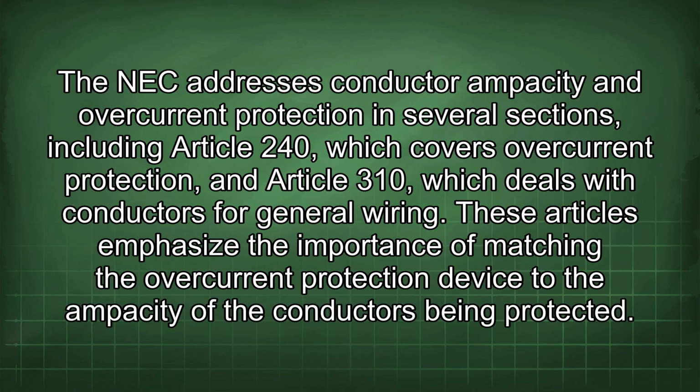The NEC addresses conductor ampacity and overcurrent protection in several sections, including Article 240, which covers overcurrent protection, and Article 310, which deals with conductors for general wiring. These articles emphasize the importance of matching the overcurrent protection device to the ampacity of the conductors being protected.